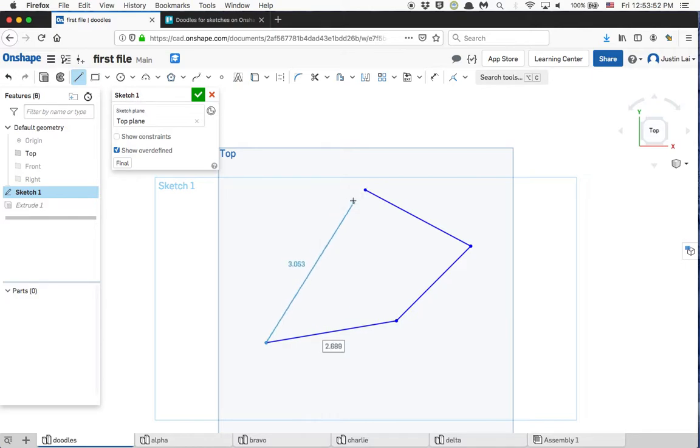And of course, this last one I'm going to let go of shift. We do want that to be coincident. But if we've done it right, all we've got are those 4 coincident relationships. So right now, you notice we've got our line tool picked up, we've got the crosshairs here. We're going to press escape to drop the tool, and let's build up the relationships.